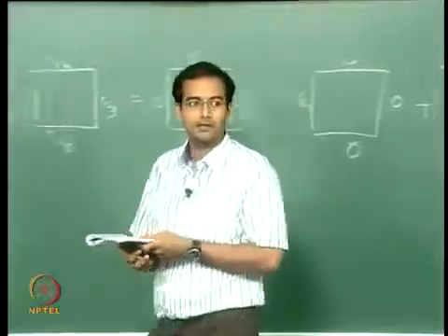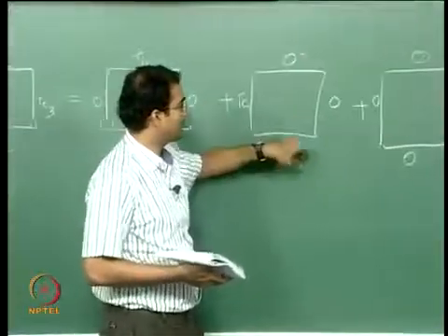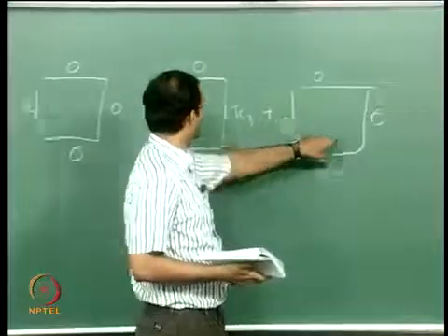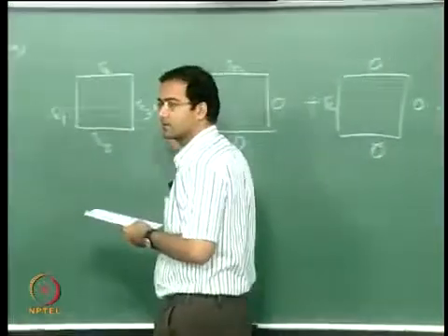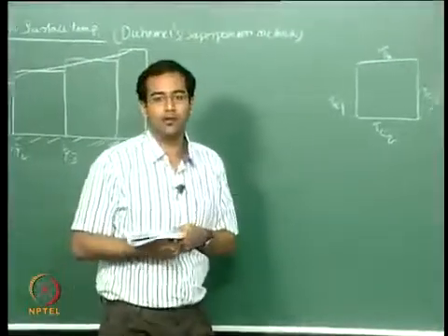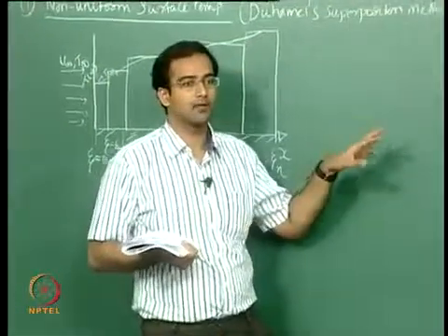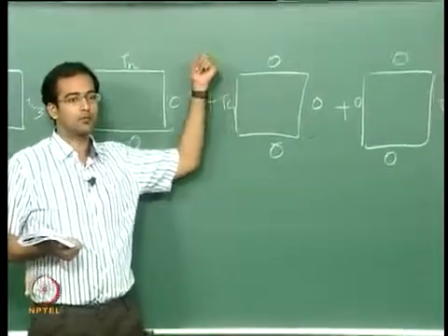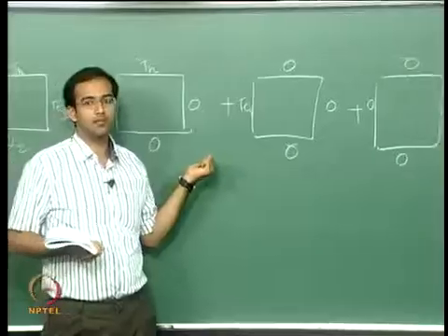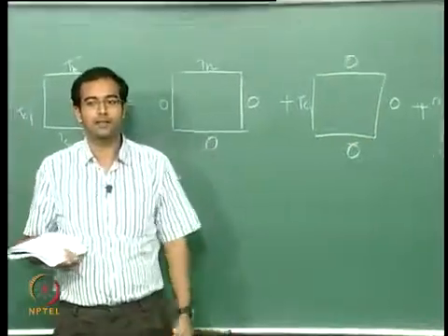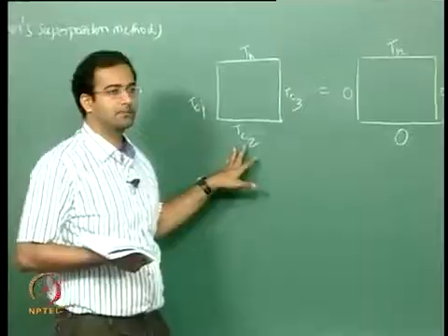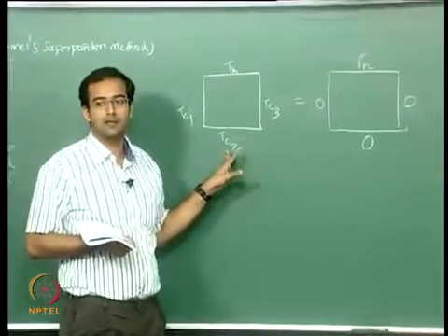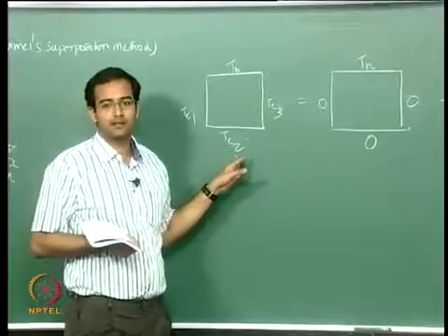So you can apply eigenvalue problems in different directions. In this case you have the y direction, and here you have the x direction. So you create 4 equivalent eigenvalue problems and you get solutions for each of these cases, each with one non-homogeneous boundary condition, and finally you superpose all these 4 solutions and that will give you the solution for this problem. This can happen only if the partial differential equation is linear, and the conduction equation is linear.